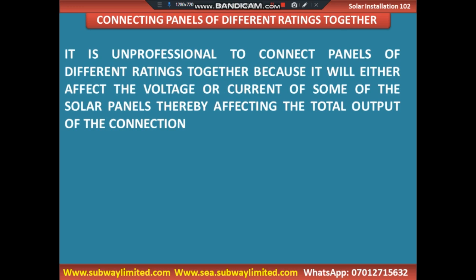We are saying that it is unprofessional to connect panels of different ratings together, because it will either affect the voltage or current of some of the solar panels, thereby affecting the outputs of the connection. So, as a professional, always guard against connecting panels of different ratings. Not that it cannot be connected.